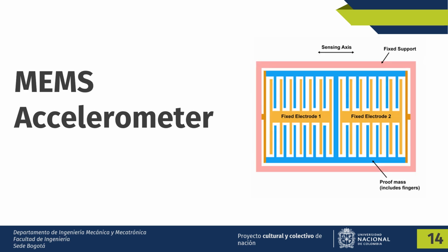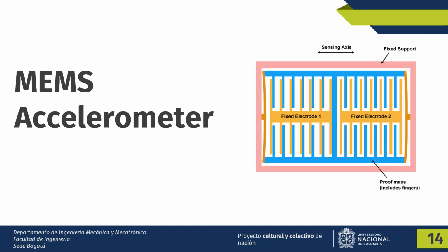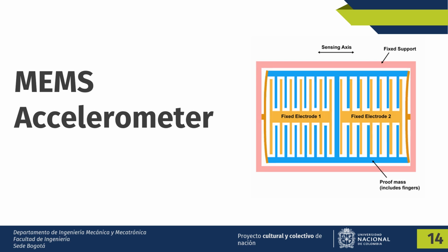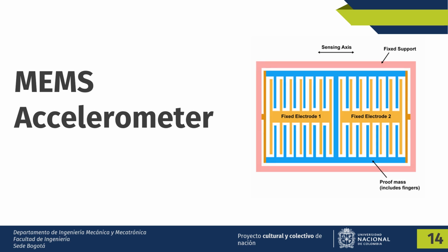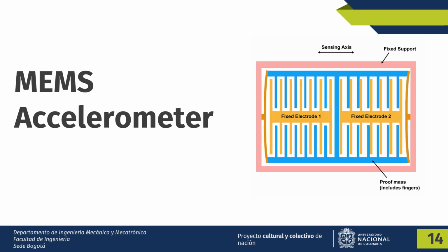Microelectromechanical system accelerometers are miniaturized devices that use either capacitive or piezoelectric technology to measure acceleration. They have a small mass suspended in between flexible structures which move in response to the acceleration. These sensors are used in every phone and consumer electronic device due to their low energy consumption and very low manufacturing cost at big scales. There are also other types of accelerometers such as Hall effect or thermal accelerometers.